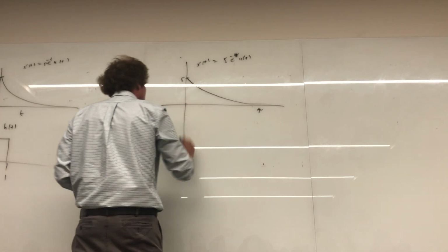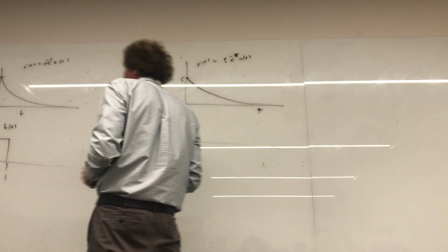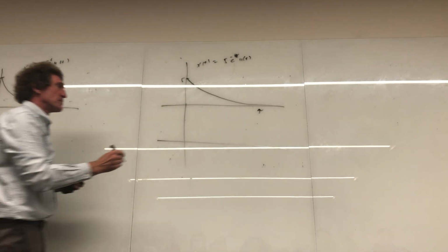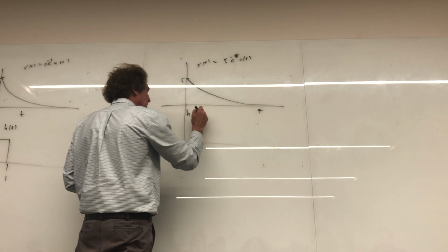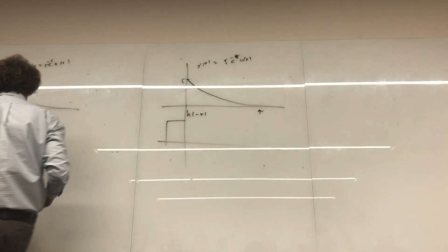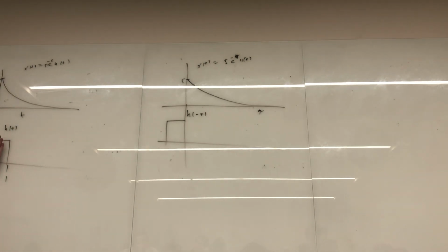Right? Now the next function, first, if this is h of t, I need h of minus tau. That's flipping it about the axis. The only thing you do is take this, and I say flip and shift, but I guess I should have been more clear. Flip it like that. You just rotate it around the stem, right? The y-axis in this case, or whatever axis that is, and just rotate it and wrap it around.